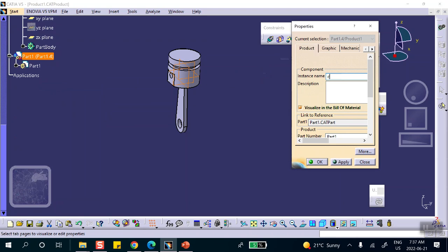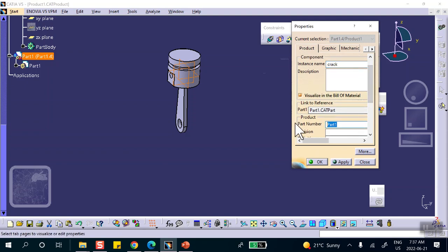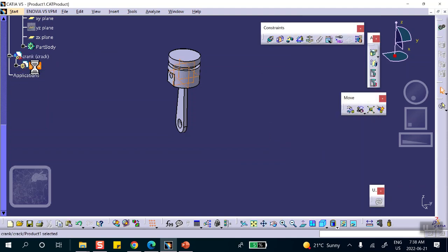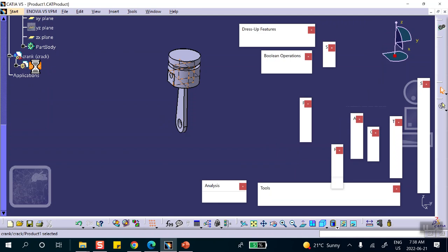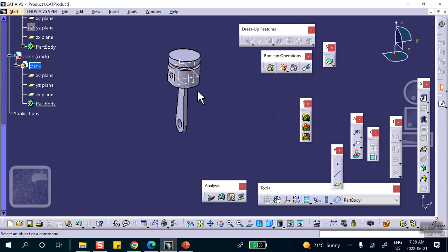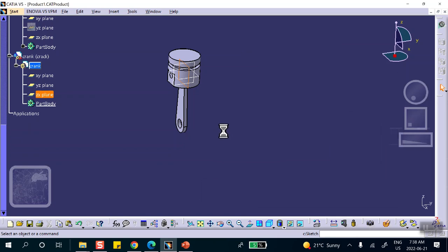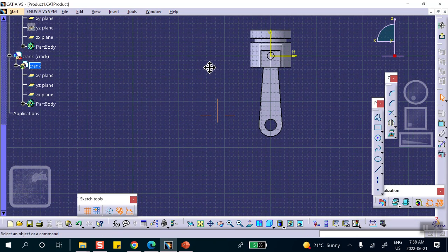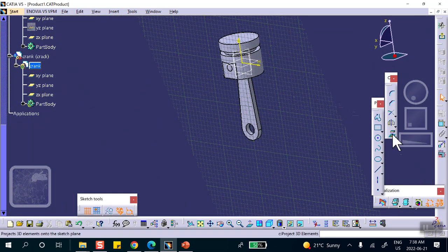crank, and crank. It's very common that people don't pay attention and they make the other part in the part that's already being made, and then of course things don't move the way they want. So double click on the crank. On that same vertical plane, I will sketch. Why don't I project the circle? Project that circle. Good. And then let's do the rest of it.